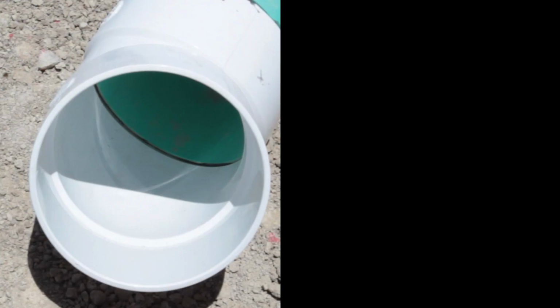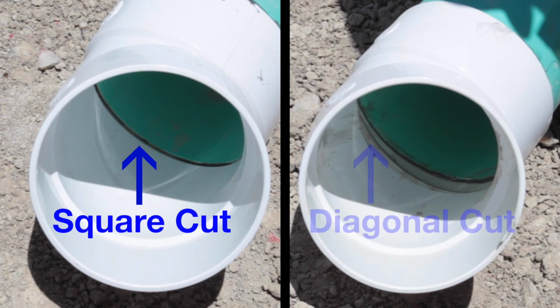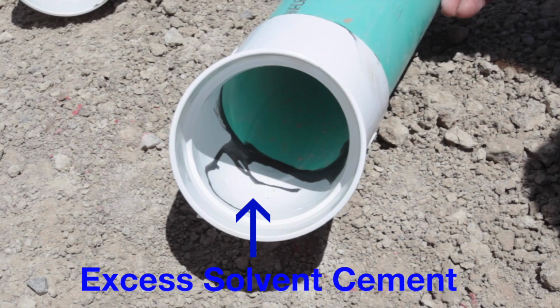Cutting all fittings squarely will make for the maximum bonding connection. Not cutting squarely, or a diagonal cut, reduces the bonding area and leaves an open joint that may cause leakage and problems with the ball test. Furthermore, over time this may cause a buildup of debris, resulting in blockage. Similarly, adding too much solvent cement will cause the same problems.